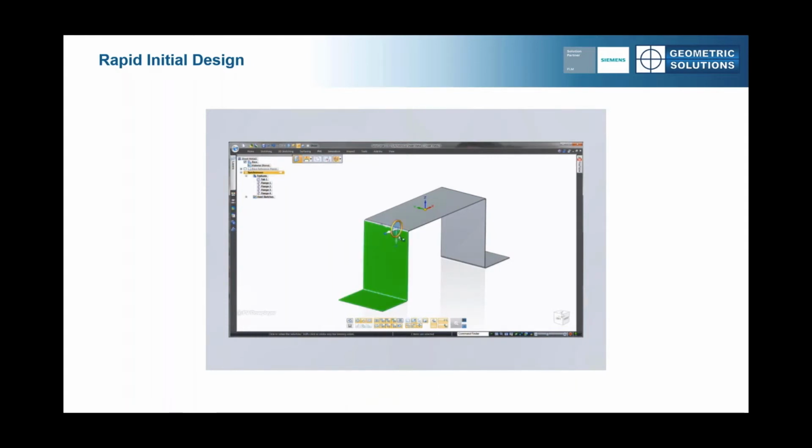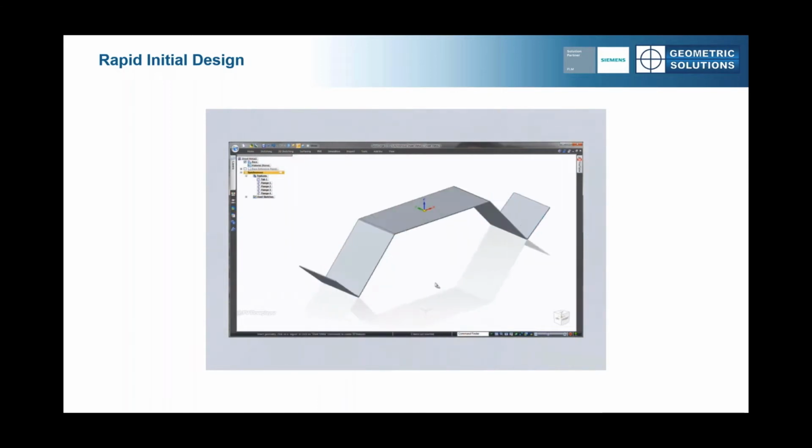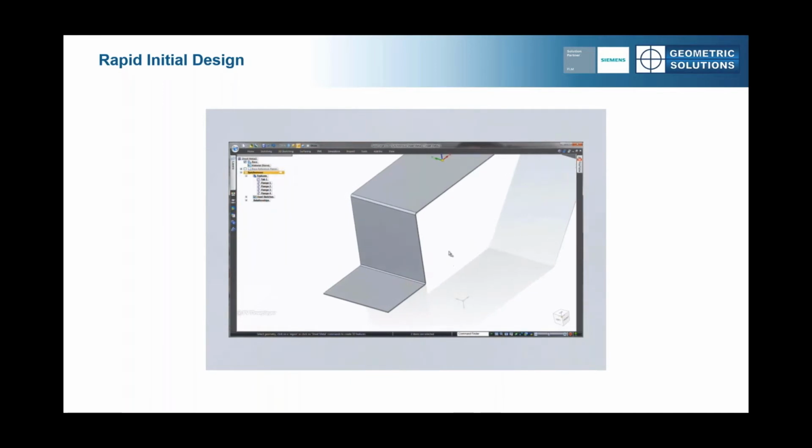We can use what we call the steering wheel, our main control in synchronous technology, to angle. But not both sides, I don't think. No problem, we'll just tell these faces to be at right angles. Just because we created these symmetrically doesn't mean there's history-based design intent tying us down, like you get in most any other CAD system. Easy.